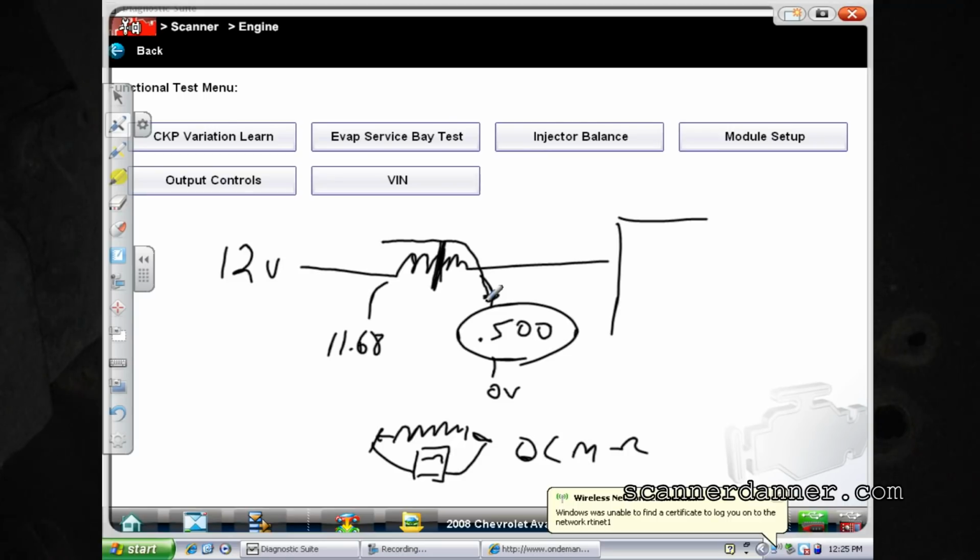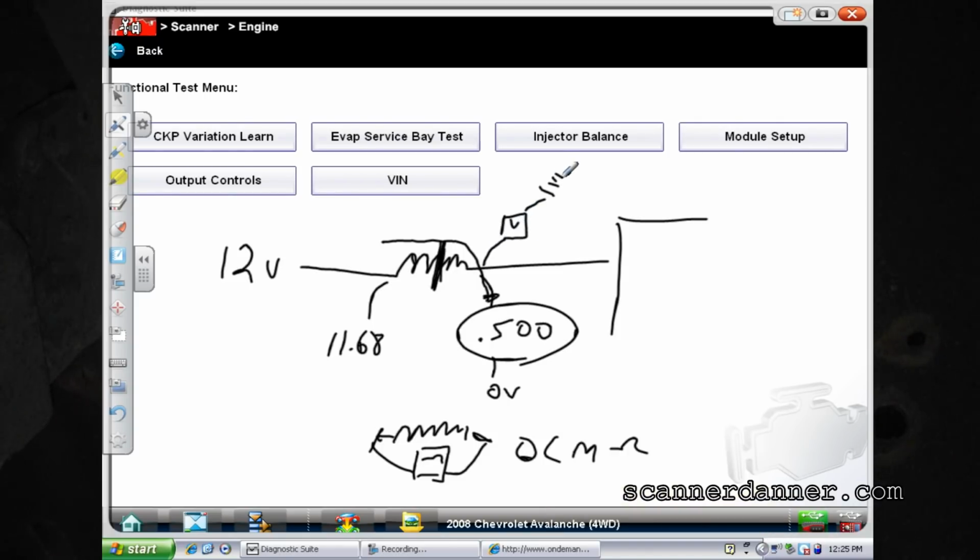The reason that I was assuming we were reading that 500 is our meter, I mentioned it being 10 mega ohms, would be the equivalent of you connecting a 10 million ohm resistor to ground. So is the meter itself going to cause some type of draw? Yes, but very, very, very small, micro amps, okay? I was thinking that the meter was causing that drop.